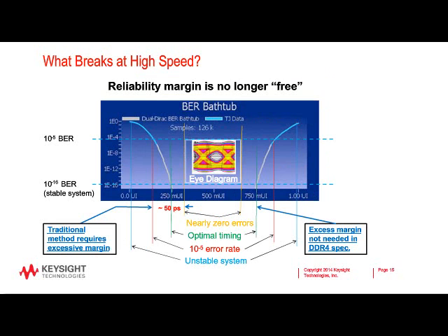When we move to the faster data rates in DDR4, with these small unit intervals compared to the RJ, we now see that the bathtub wall is quite shallow. And so if you don't know accurately where this gray extrapolation is going, you have to pad quite a bit. These yellow vertical lines now are padded for the uncertainty in the dual Dirac approximation.